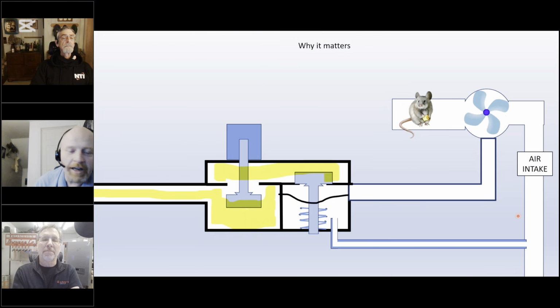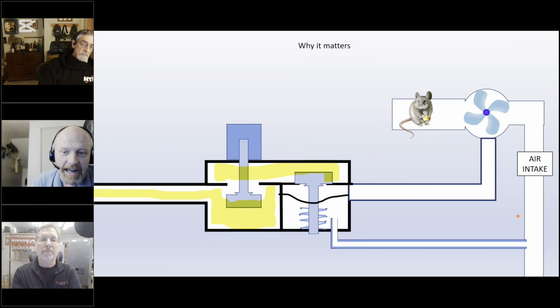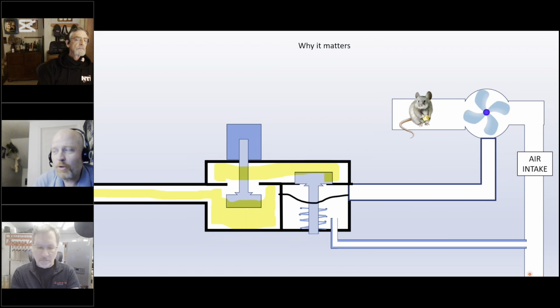Run the boiler at full fire. This is for residential size boilers, so I'm going to say that's basically the 200 and down. If you're running 3-inch venting, you're going to have a negative pressure somewhere in the region of 1/4 of an inch, so 0.25 inches water column of suction pressure in the intake pipe.